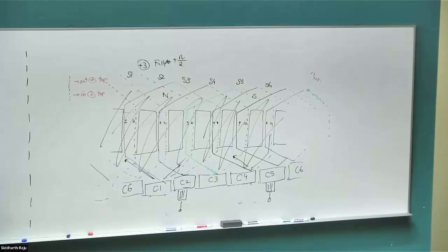Right? So when we are shorting this coil, is this going to be a problem? Is there going to be current flowing in the coil? There is, but if you're shorting a conductor that's carrying current, that's fine. You don't want to interrupt a conductor that's carrying current, but it's absolutely fine shorting a conductor. You can have an inductor and you can short an inductor. That's what the freewheeling diode in a buck converter that we saw does. When you break the switch open, the diode is basically shorting the conductor. That's absolutely fine. What is the bigger problem? What shouldn't you short?